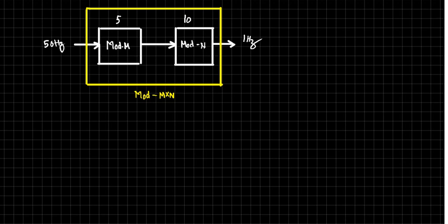I have shown you a video in analog electronics class where I said that they are tuned to some particular frequency in such a way that when these frequency dividers are applied to that clock frequency, you will get divided clock frequencies. Say for example, you need to count seconds. You require a clock which is actually counting seconds, right? The frequency will be quite higher. If you need to count minutes, how much is the factor? 60, right? For each 60 seconds, it will require 1 minute to be counted. So that is where there is a demand for a divide by n counter. I mean, a frequency divider is required there.